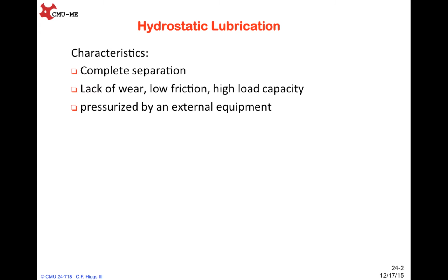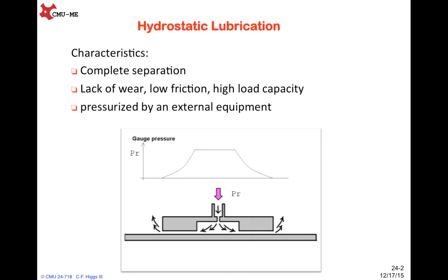It also differs from hydrodynamic lubrication in that the contact pressure is generated by an external pump instead of by viscous drag. And the picture here shows what the system looks like. It is always used in equipment with extremely low speed, as the hydrodynamic film cannot form.